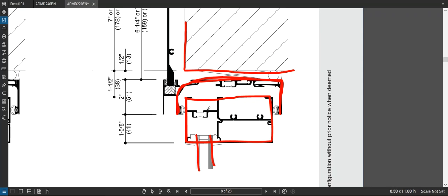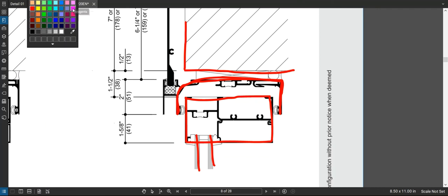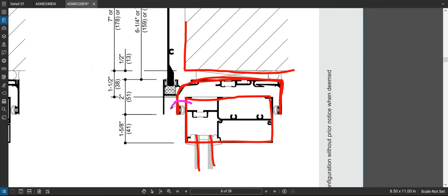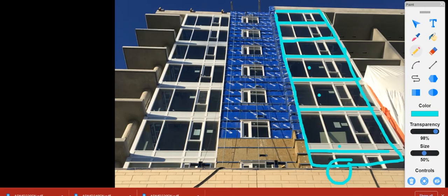And really, from a building envelope standpoint, what you're relying on in this system is pretty much that seal there and that seal there. Now you can put compressible insulation in here and that type of stuff, but really it's heavily dependent on that and that. So you do see a lot of these buildings where that system's used, and really your building envelope is a pretty weak point basically. A top of slab and bottom of slab in these systems.